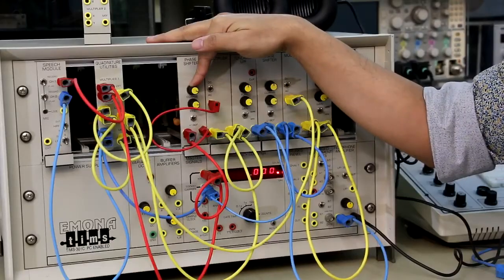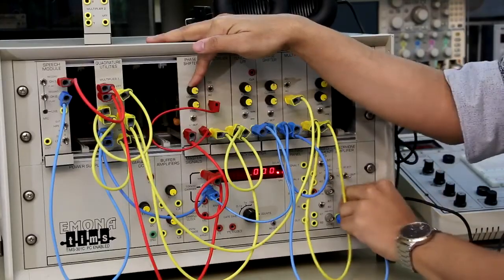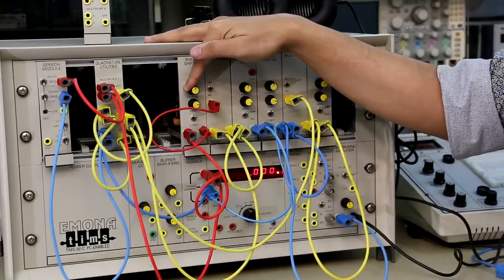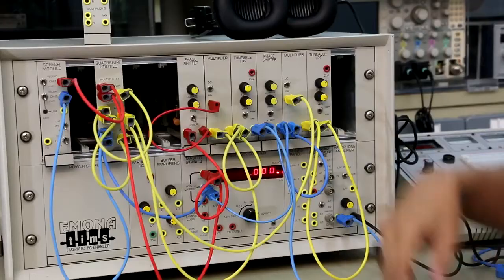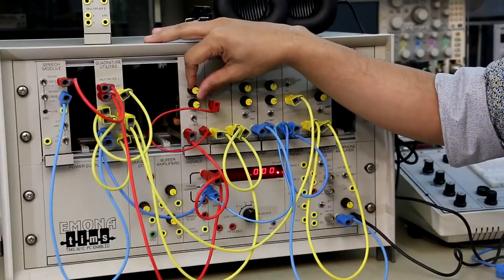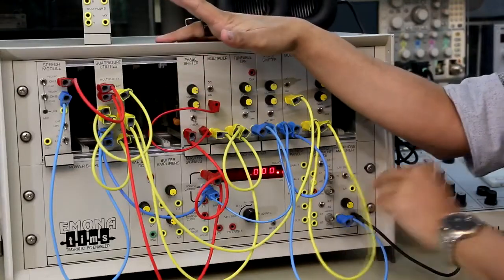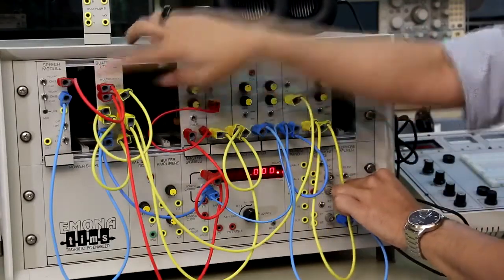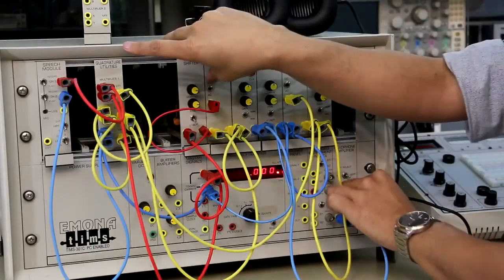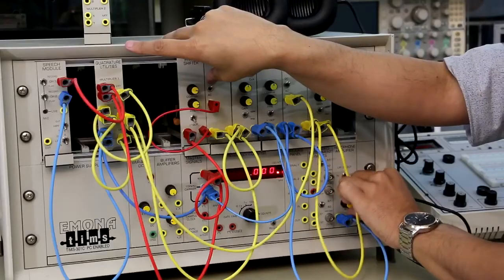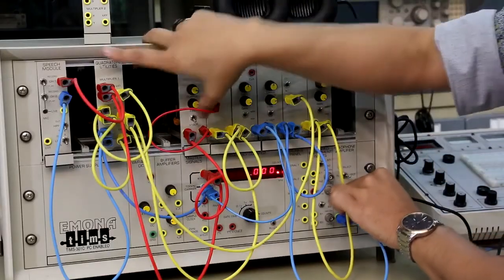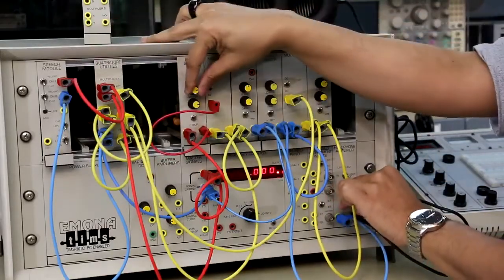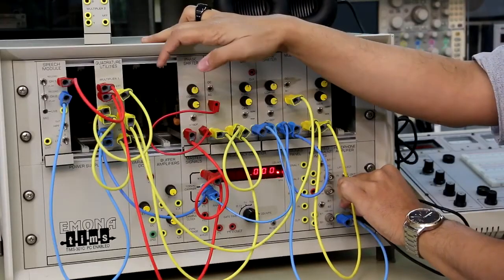You see, there's an interference. So if you want to fix it, I have to use a phase shifter. So if the carrier that is used here and the carrier that is used here have some phase difference, it is going to cause interference. As you can see, there's an overlapping between the messages, and the best way to fix that is to have a phase shifter that will clear it out.